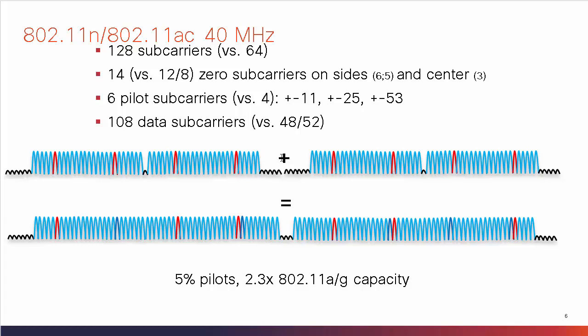But then as you see at the plus location, we have the top of one channel on one side and the bottom of the other channel on the other side. We don't need that many null channels on what will now be the middle of the frequency. So we're going to use only 3 null channels here, and of course we can get rid of those null channels in the middle of my previous 20 MHz because now these are right in the transmission mode, so we don't need those for alignment. So we use the one at the top to avoid overlap, just like the one at the bottom, with the neighboring channels, and then we use these 3 at the middle for calibration and identify the middle of the frequency range.